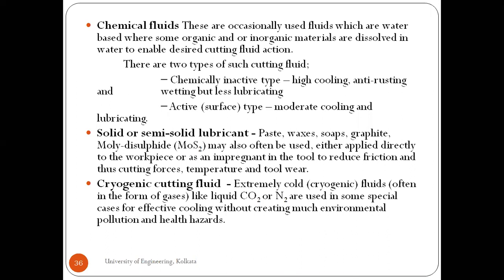Cryogenic cutting fluid: liquid nitrogen, liquid carbon dioxide, not oxygen. I just told oxygen before, but not oxygen. Liquid carbon dioxide can be used. Liquid nitrogen. These are cryogenic and definitely without creating any kind of environmental pollution or health hazard. It provides effective cooling.